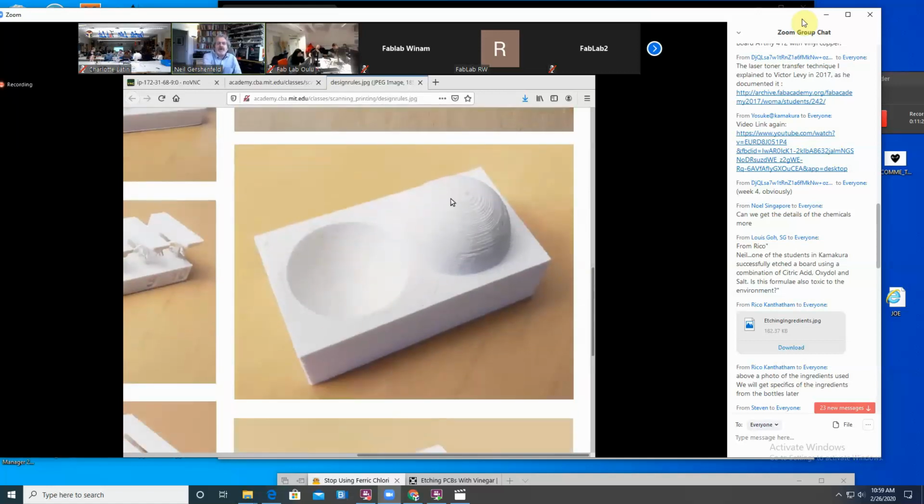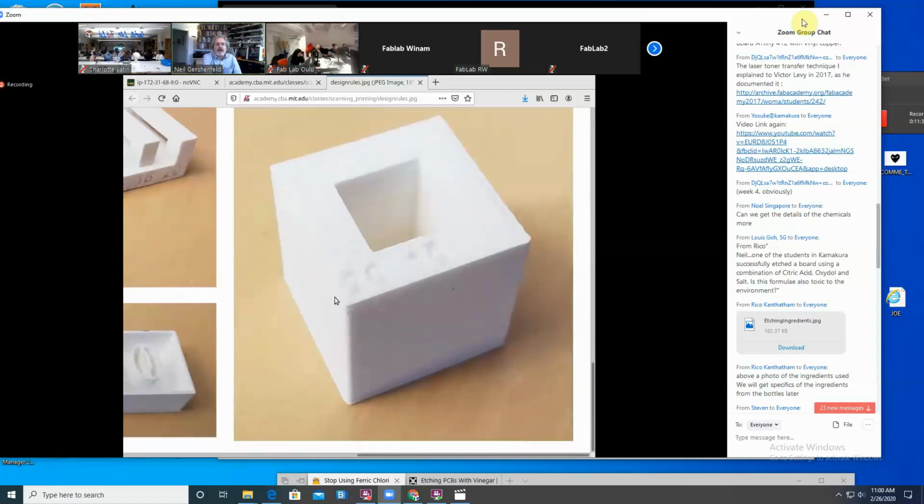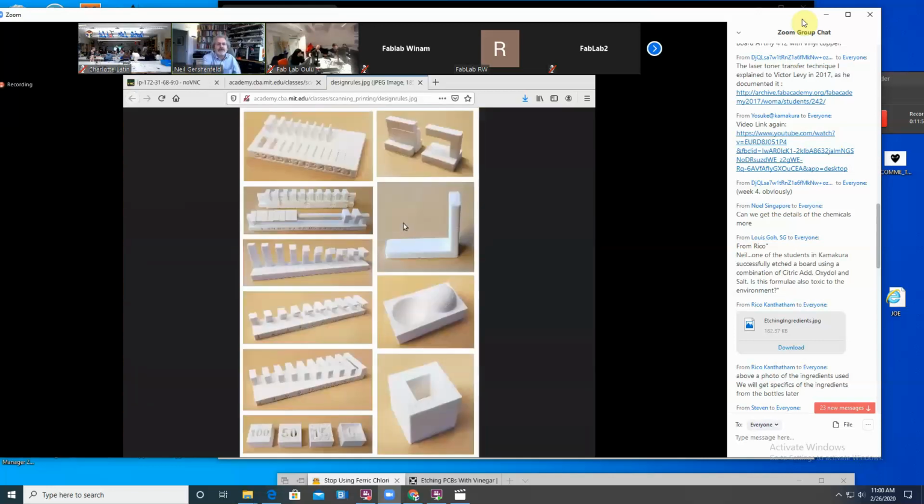This one is showing the apparent surface finish is a strong function of the angle of the print, where the steps are more noticeable here. And then this one is printing a part with a designed outer and inner dimension. And if you actually measure it, there can be quite a difference between the actual dimension you get and the dimension you thought you get. And it can be a difference in an outer and an inner dimension.